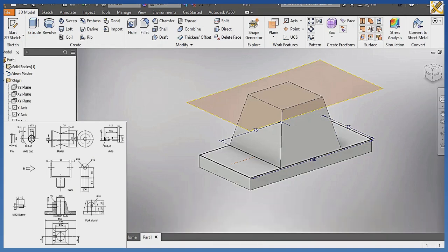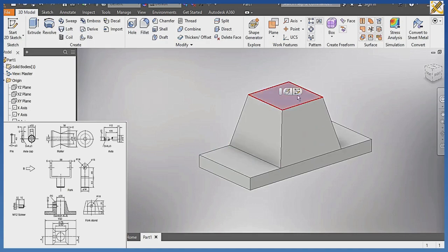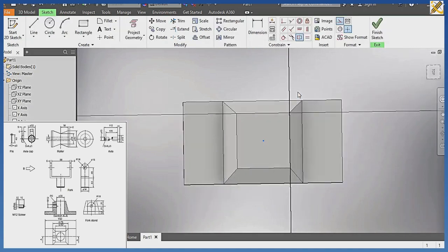After doing that, I'm going to come to sketch 2 and hide visibility. On sketch 1, I'm going to hide visibility. Then on the work plane, I'm going to hide visibility also. Next is clicking on this surface right here, clicking my create sketch in that order.